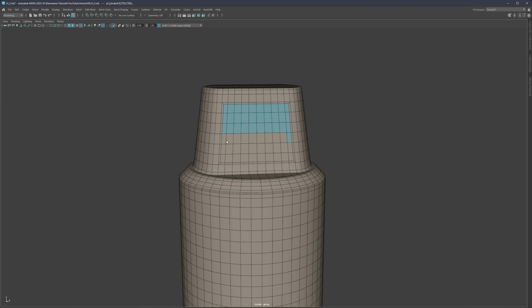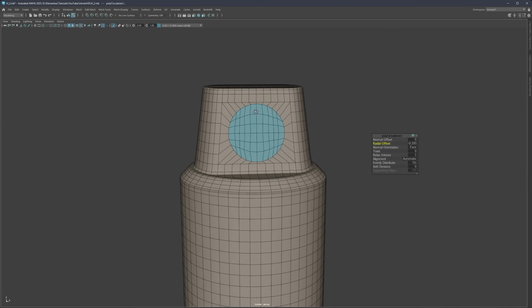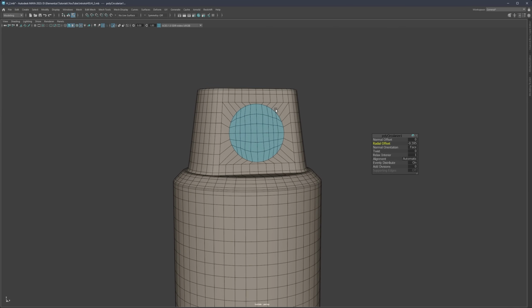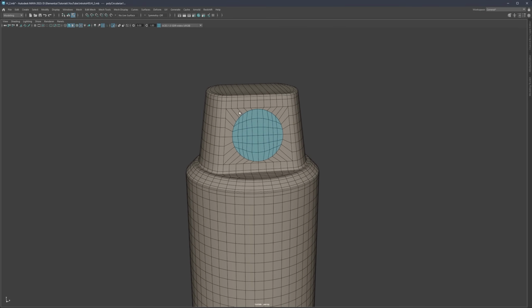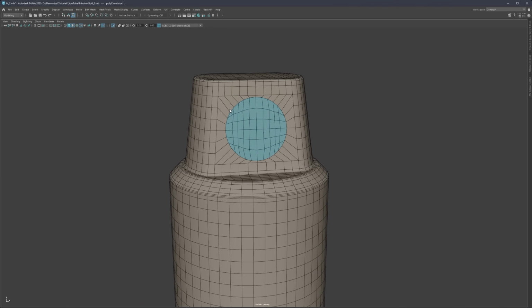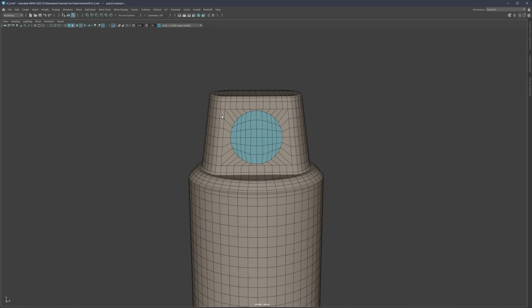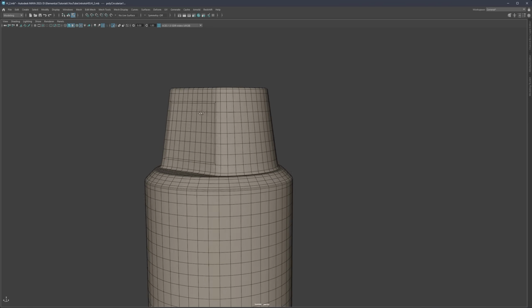Now we select all these parts and circle these components, go to radial offsets. And let's say now we create a circle. But on the other side, something went off and we don't have a circle. So you actually do not need to undo this. You don't need to undo and do the same thing on the other side.